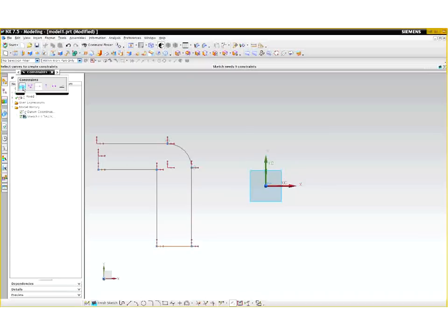I'm going to select the fixed constraint option. When I select fixed constraint, so I'll left click this fixed constraint, you see that both of the indicators that allow me to move this object up and down are no longer there. So let's try to move it up and down. We can't. Try to move it left and right.